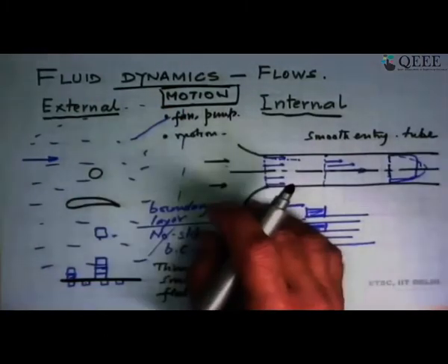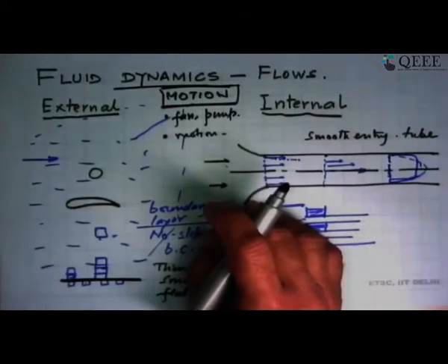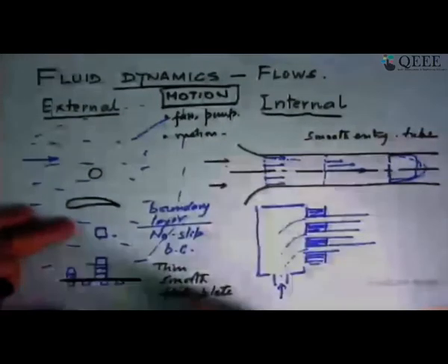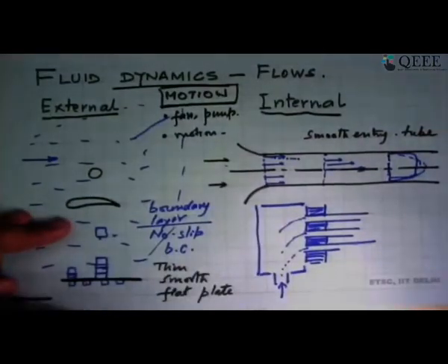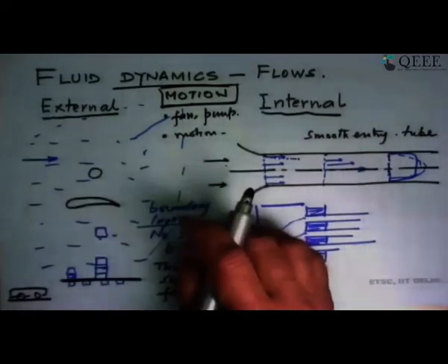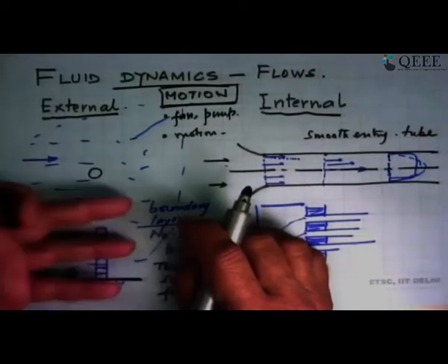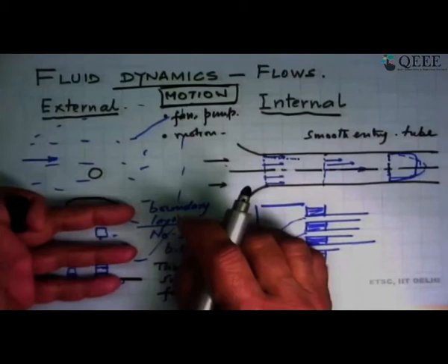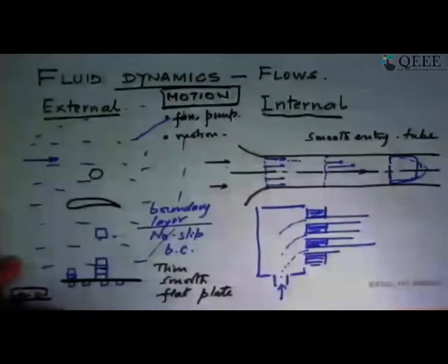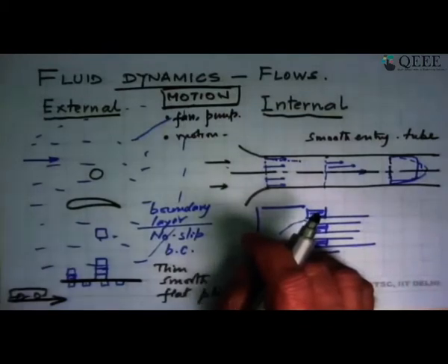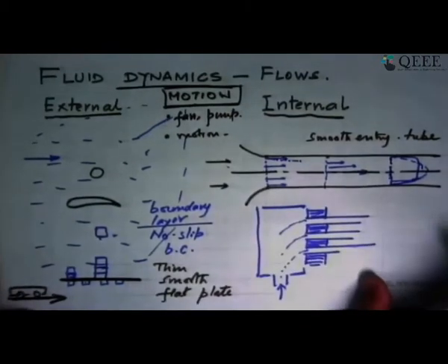Same thing we have to do with an automobile or a motorcycle or a train, but there is a complexity. In that, you have a surface road on which this vehicle is moving, and if I have to create exactly the opposite situation like we did for the aeroplane, I will not only have to make the vehicle stationary and put airflow on it in equal magnitude in the opposite direction, but this road also has to be made moving. Only then the fluid mechanics will be preserved. This is quite a bit more complicated.